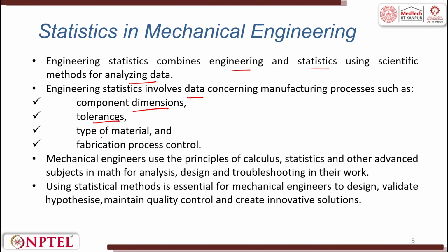Type of material, that is very important as well. If you are talking about boilers, we will talk about nozzles made out of material that could bear the high temperature of the steam. Generally, mild steel nozzles could not be used directly there. SS, copper, these kinds of nozzles would be used there.